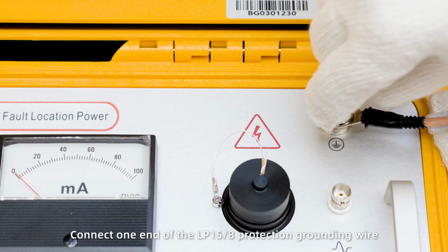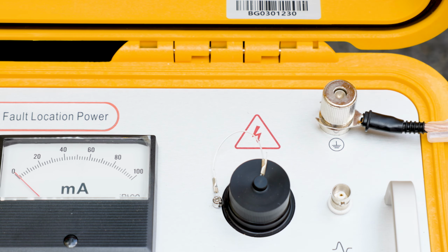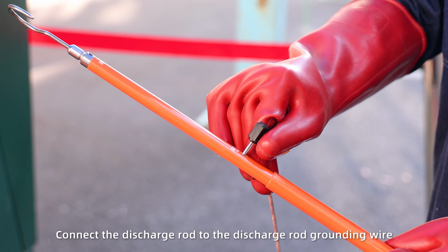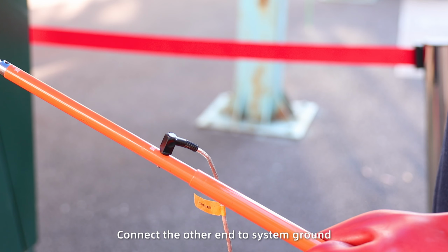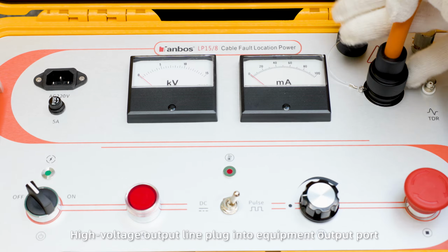Connect one end of the LP15-8 protection grounding wire to the protection grounding post. Connect the other end to system ground. Connect the discharge rod to the discharge rod grounding wire. Connect the other end to system ground. Plug the high voltage output line into the equipment output port.